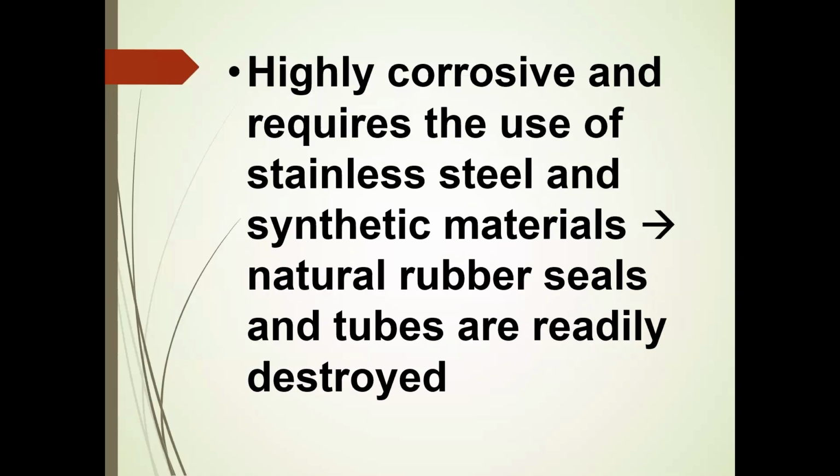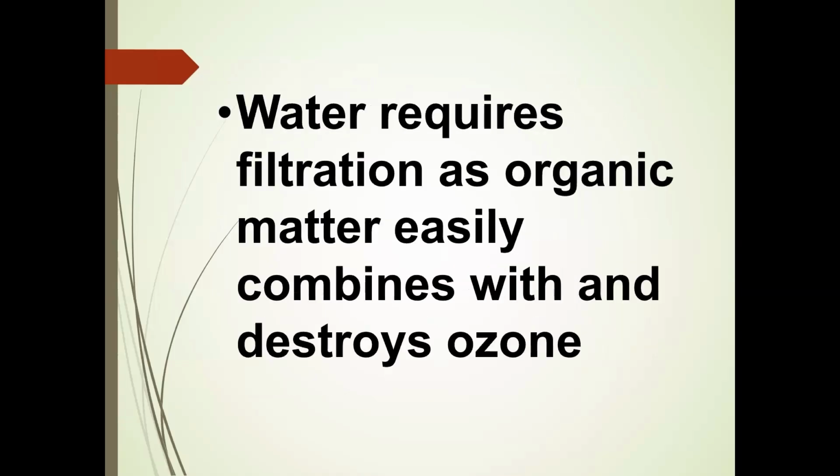Ozone is highly corrosive and requires the use of stainless steel and synthetic materials. Natural rubber seals and tubes are readily destroyed by ozone. Water to be ozonated must be filtered, as organic material easily combines with and destroys ozone.